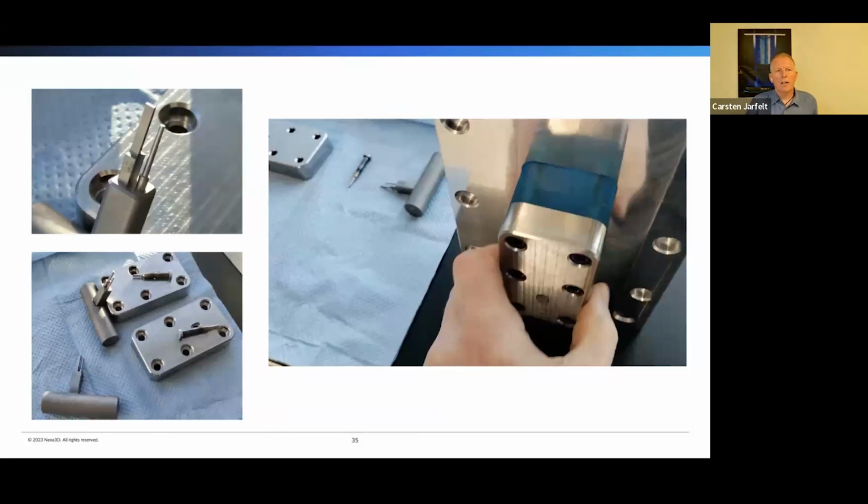Another version is the reverse: not dropping in an insert, but dropping in metal. This is a project we did for a team that wanted to explore in the packaging space how things could work, feature-wise, but also surface quality-wise and spray channel-wise. So think of this as a way of embedding, in this case, metal pins into, if you look at the right photo, the xMOLD resin there.